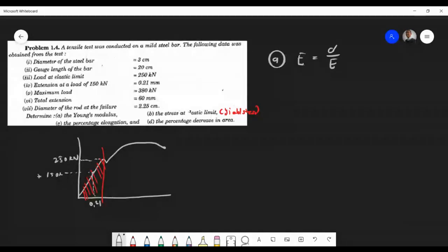Because you're talking about a steel bar, it'll be very useful for you to know your material properties. For instance, if you're talking about steel, we're expecting an elastic modulus of 200 to 210 GPa. Aluminium around 70, copper around 100. Each ferrous or non-ferrous metal has its own range, and I'll give you a more comprehensive table with these properties. Nevertheless, let's go back. So we're expecting a value around 200.